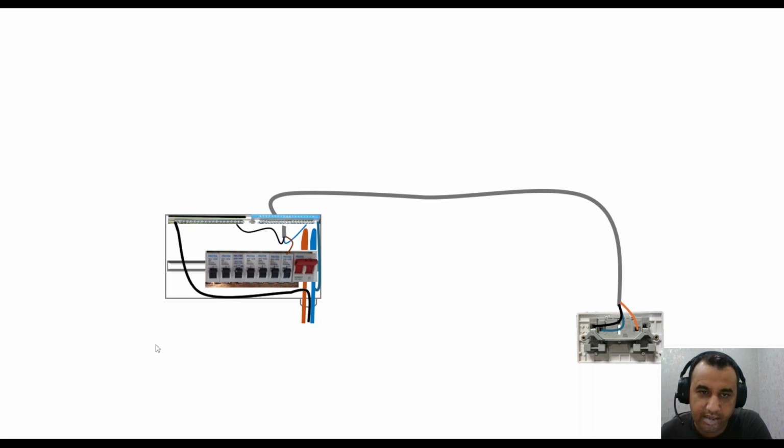What we've got here in this consumer unit are these meter tails. They're coming from the meter, and from the meter they go to the cut-out. From the cut-out they go to the transformer, whatever the line. If you've got a distribution line outside to your local transformer, that's where these are connected to. Well, in this video, I've got a TN-S system.